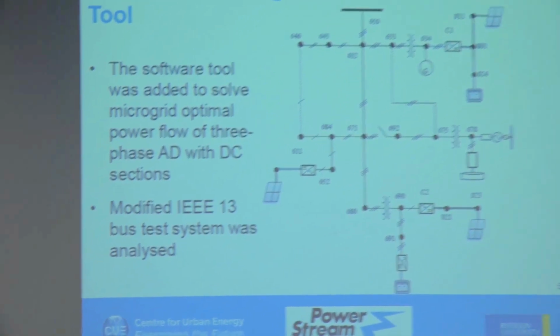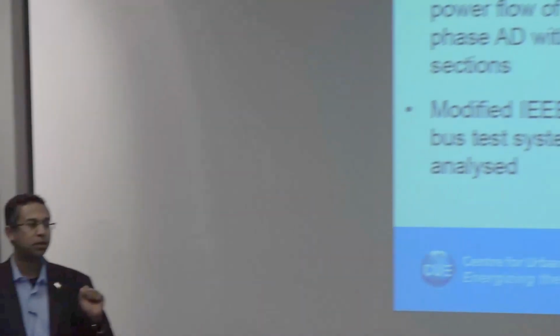what we could also do is take the same set of equations, pose those equations as constraints, and then you can optimize to whatever you want within the AC-DC network. So we can create an optimal power flow tool in a very easy fashion. So that was the next step that we thought of doing. Now, the purpose of that optimal power flow tool was to plan for the network, to optimally run the network so that you can have minimum cost or minimum generation.